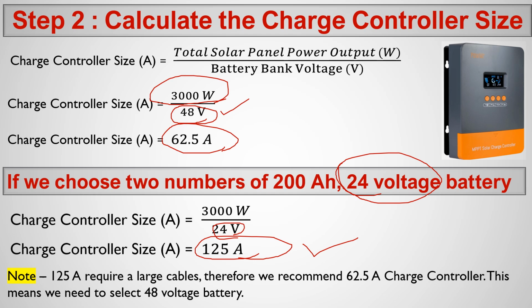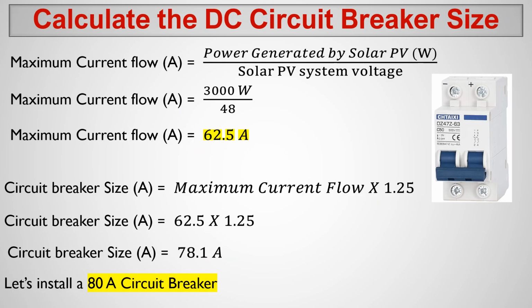In electrical engineering, we don't want to increase the current in a power system, because increasing current always causes more cost: we need larger wires, larger breakers, and safety equipment. That's why we don't want to increase it. So far we have calculated most of the things. Okay, so let's come to the next one, the breaker size.